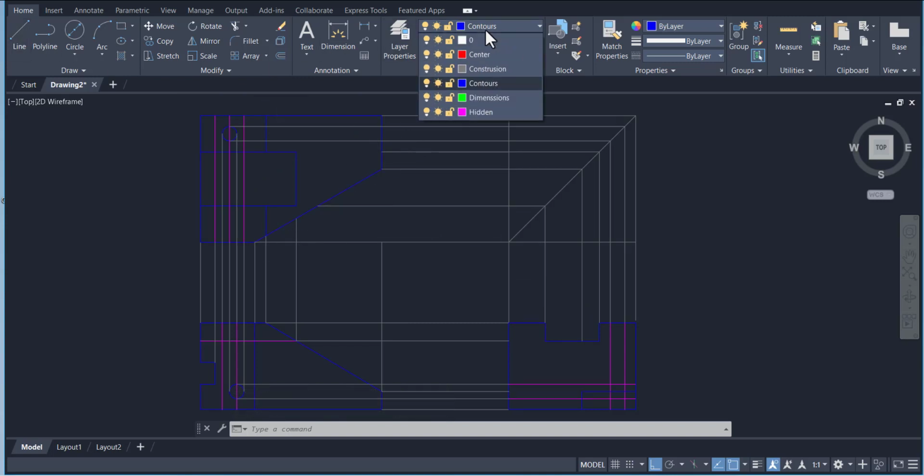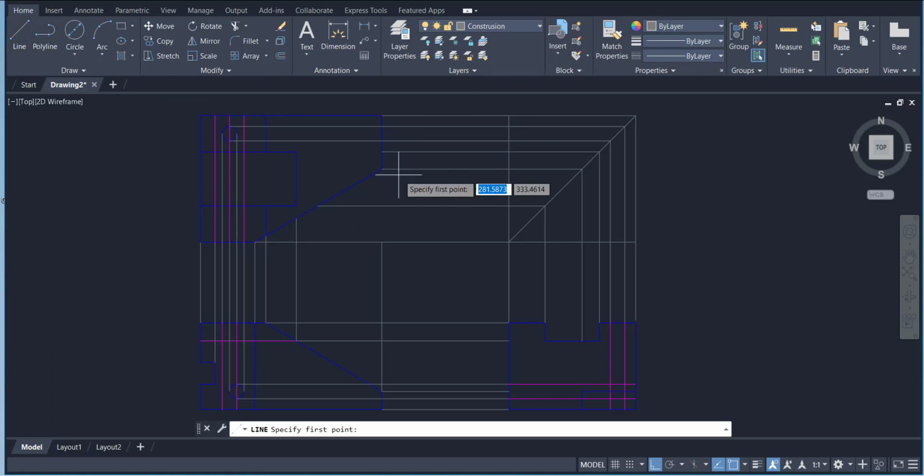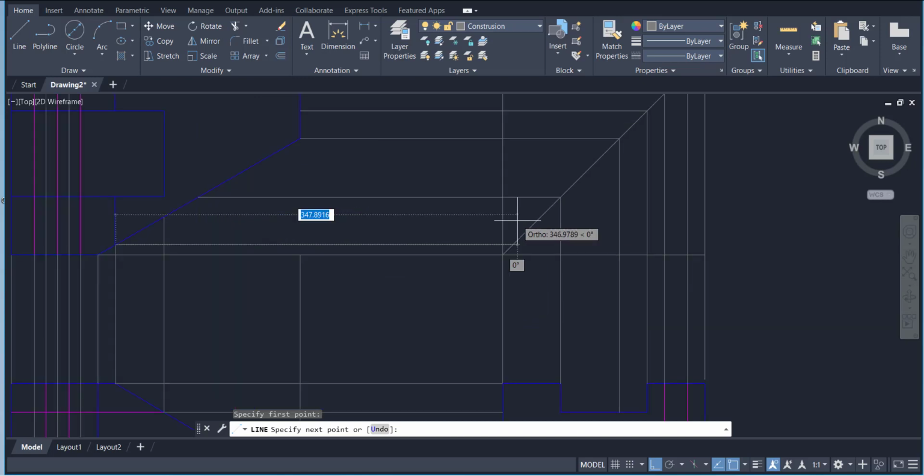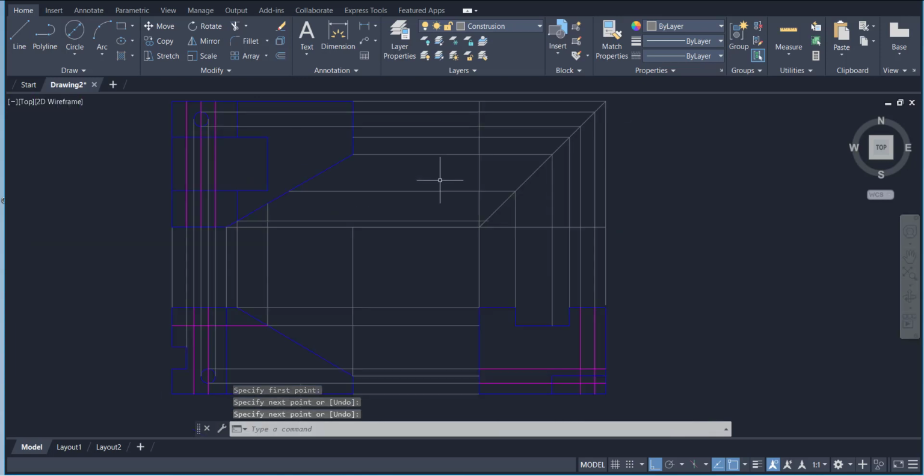So when we transfer the view, we construct a line from every point. So this point is remaining, so transfer it to the middle line, make sure it's not auto tracked, and then I'm going to trim this point and a line from this point till this point, and just extend this line.